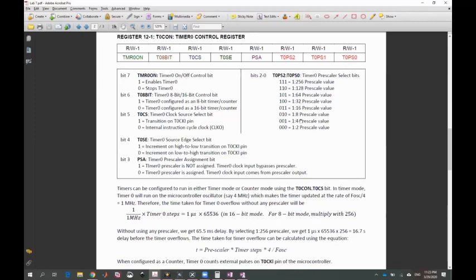For example, if you have 8 coils inside the DC motor and you are using the Hall effect sensor, then select the prescaler 1:8 and select 1 here on this pin, the timer 0 clock pin, and it will keep on incrementing on every 8 pulses.